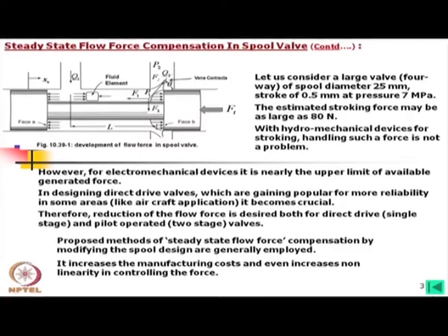This is very simple, just a step down. Instead of that, if we would like to modify this profile, naturally the manufacturing cost will be more and it even increases nonlinearity in controlling the force. Sometimes due to this curve or maybe some profile which I will show, nonlinearity will increase, but still reduction of this force is required.